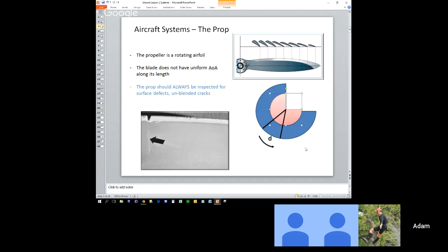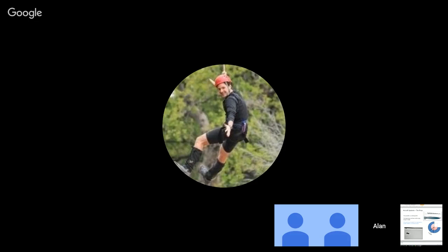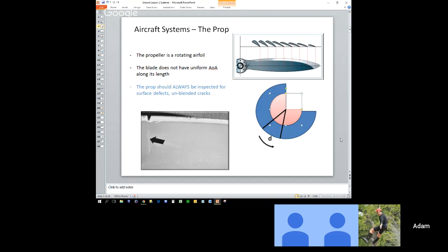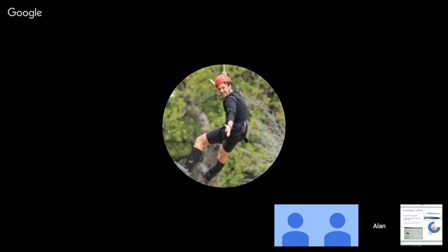Okay, everybody understand, any questions on the angle of attack notion there? Makes sense? Just to repeat, you said as the angle of attack goes down, speed goes down, right? As the speed decreases, if you want to generate the same amount of lift, you've got to increase the angle of attack. Got it. Yeah. Okay, I'm with you. Yep.